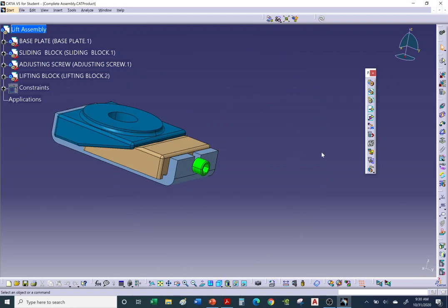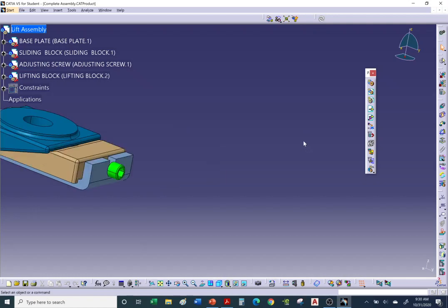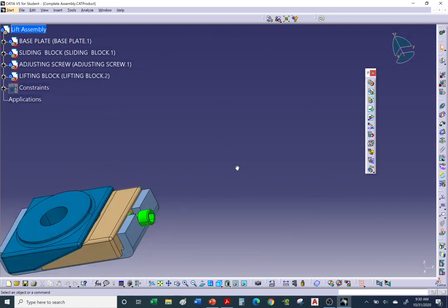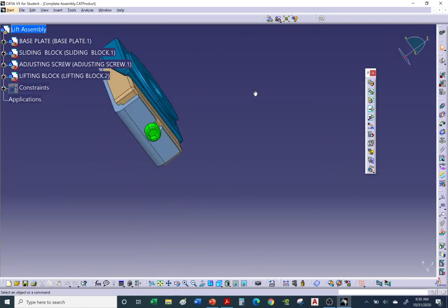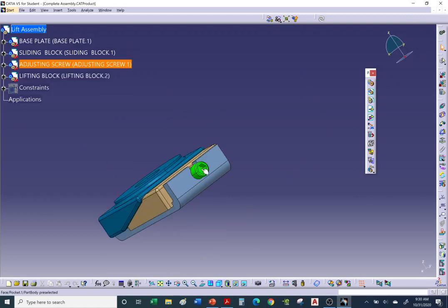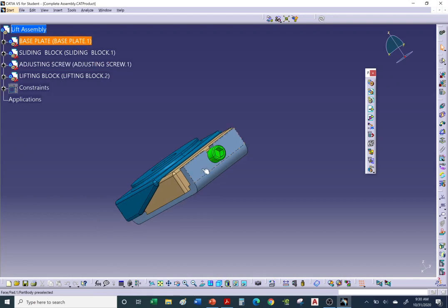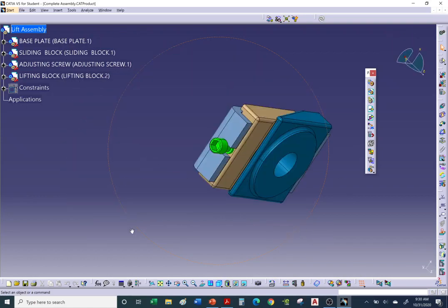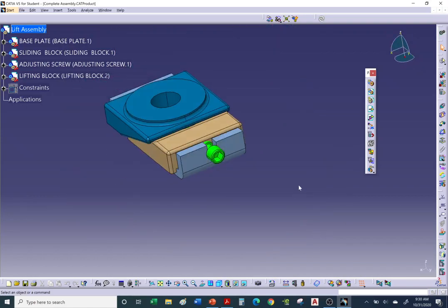Keep that in mind because if you wheel click out in the middle of space, notice I clicked in the middle of space. I clicked some random point and it moved it here and it moved everything over. So now when I rotate, it's going to rotate about some random point that I had previously picked. So I hold on to the wheel, the right button. Notice that it's rotating about some random point that I had selected with the wheel earlier. Okay, so keep that in mind. If I want to rotate about the bolt, click with the wheel, let go of the wheel. Now I'm going to hold on to the wheel, hold on to the right button, and it rotates about the bolt, as you can see. All right.